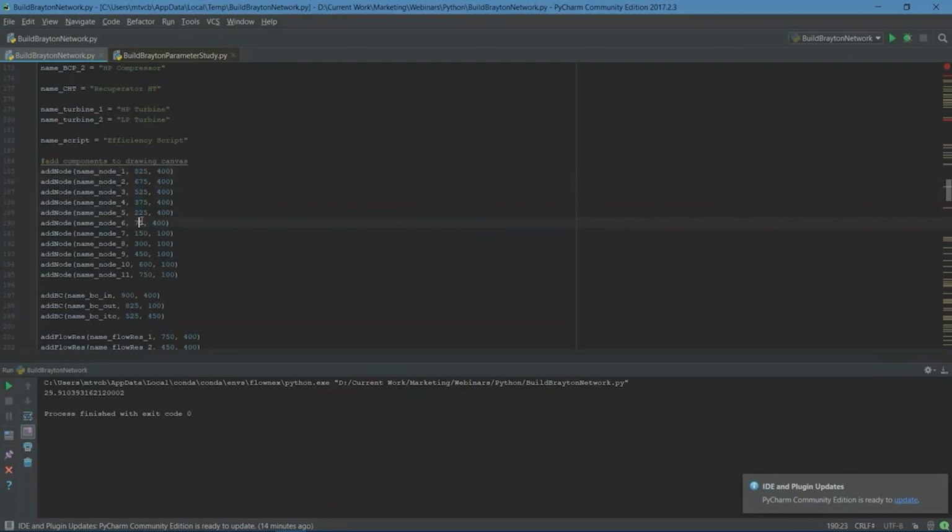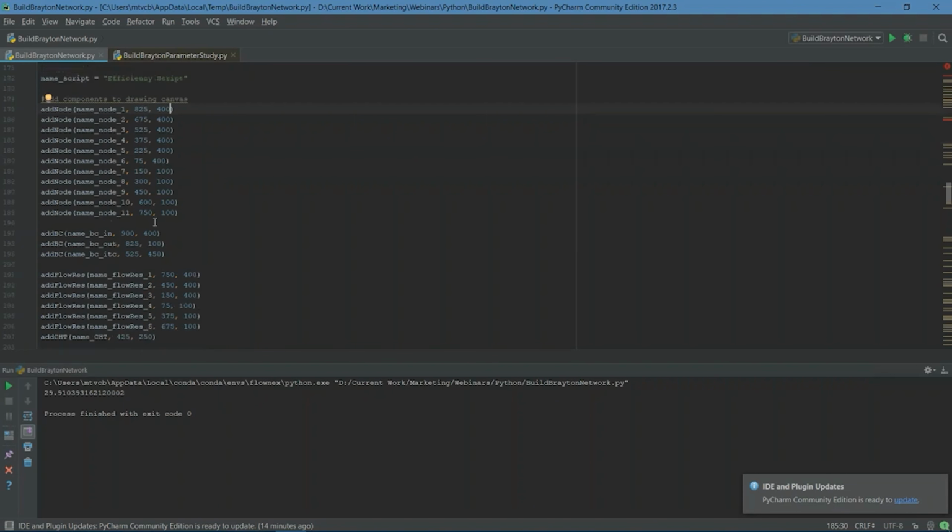In some kind of scenario where you're reading in a lot of geometry from a data file, I'd recommend you put in calculations for the X and Y coordinates. So set a variable for the X stepping and the Y stepping, for example, and then inside of the for loops that read each row or each column, automatically increment the X and Y positions based on a counting variable and then a predefined step. If you'd like more information on how I've done this in the past, please feel free to send us an email. I'll give you some examples there.